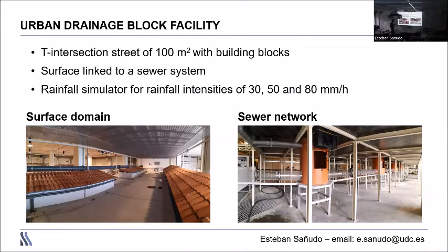The facility has a 100 square meter area. It's a very big facility, and we also have one of the biggest rainfall simulators equipped in the facility. You can see the rainfall simulator there. The facility is also linked to a real sewer system with pipes, manholes, and an outflow. And the rainfall simulator can generate intensities of 30, 50, and 80 millimeters per hour with very accurate results.